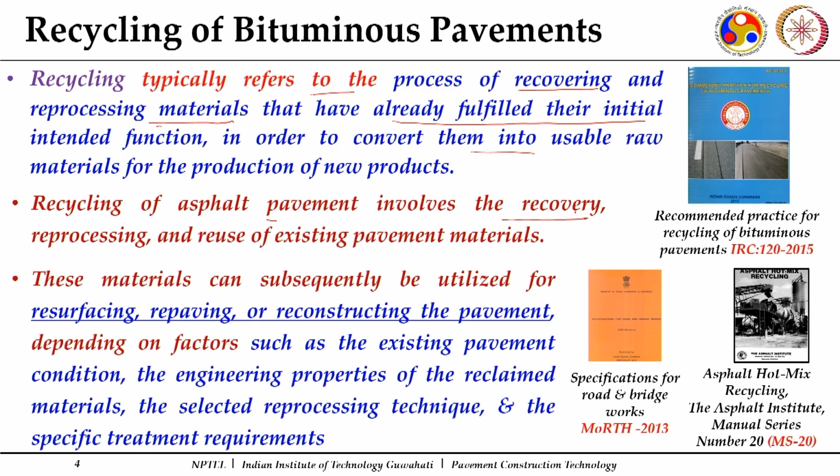So, what are the main steps involved in recycling of asphalt pavements? It involves the recovery of the existing material and reprocessing it, with some addition of aggregates, some addition of binder, rejuvenating agent, and certain additives, and reuse of existing pavement materials. By this, we are reusing these materials to construct one or two layers of bituminous pavements.